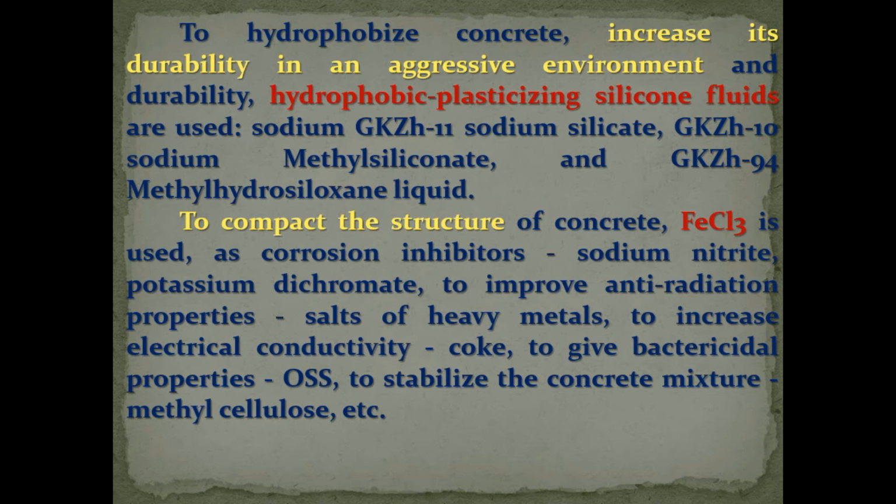Hydrophobic additives increase the durability of concrete in aggressive environments. Hydrophobic plasticizing silicone fluids are used: GKZH11 sodium silicate, GKZH2 sodium metallosilicate, and GKZH94 methyl hydrosilicate liquid.